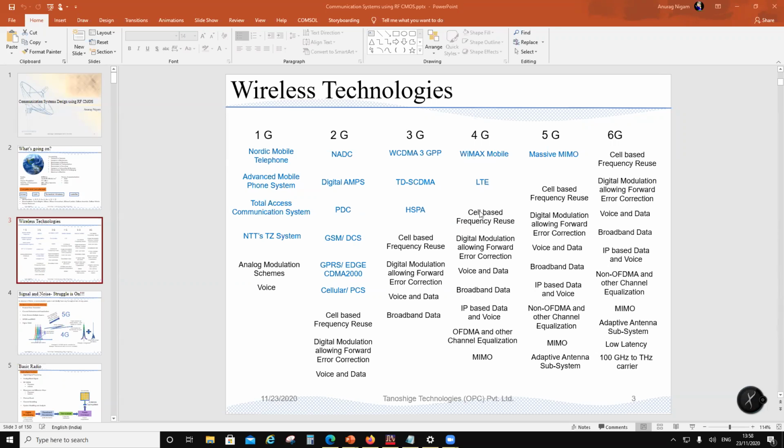So that basically carried on to WiMAX. That is 802.16 a/b/c/d/e. The mobile version is called e. That WiMAX was in the 3.3 gigahertz to 3.9 gigahertz band, right? So WiMAX didn't pick up. Before it could pick up, there was 4G. And in 4G, we do not have a base station. We have access points, much like computer communication, right? Now, long-term evolution. What is happening between 3G and 4G is the following. There was a lot of channel estimation going on in 3G.